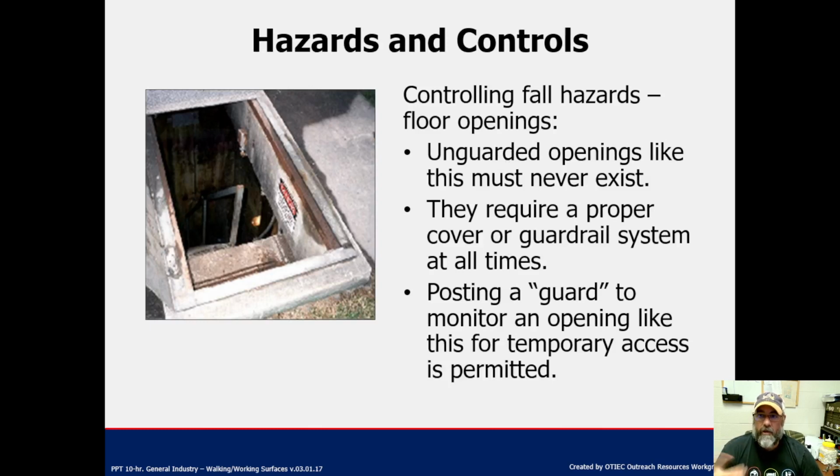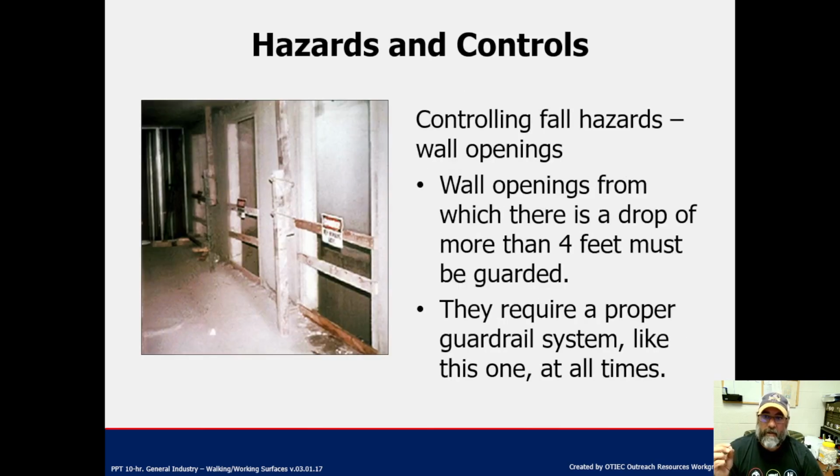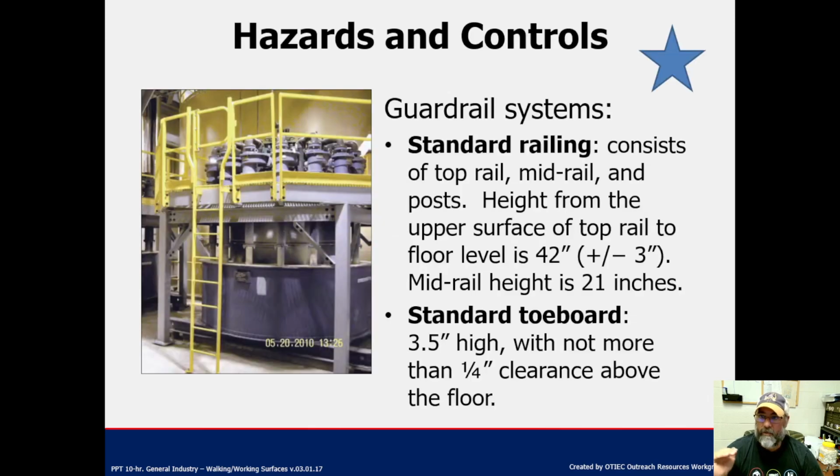Open pits. Those need to be guarded all the way around. An individual walking by, nowadays looking at their phone as they're walking, can fall into pits like this. If you remember from the videos that were optional, you see an individual opens up a pit, another individual falls into it. So these things do happen. If there's more than a 4-foot drop, they must be guarded. So we see here toe guards, we see guardrails. On here we see more toe guards, toe boards, hand railings, little star there.